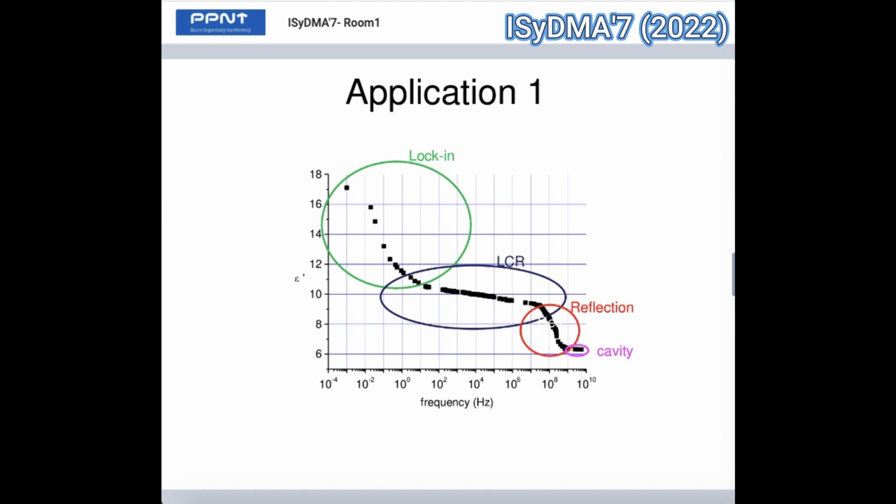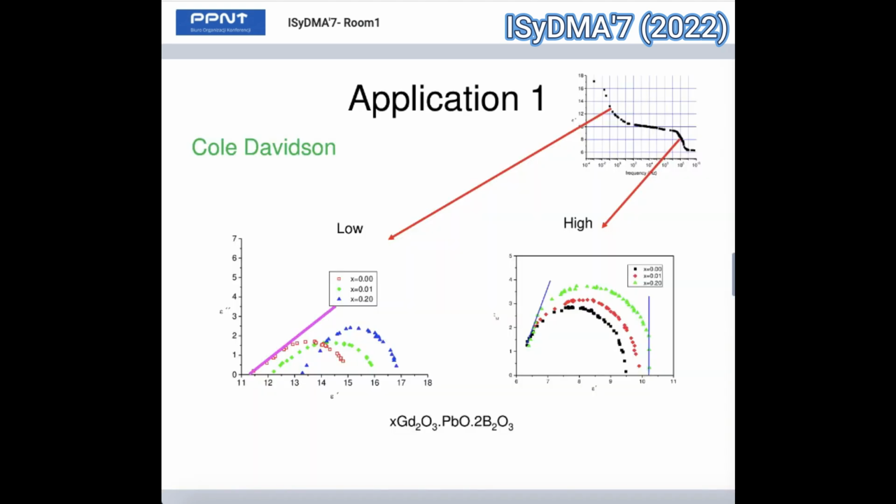And at very high frequency, let's say microwave frequencies, I use a cavity resonant method. That is a method that, in my case, for each cavity we can use only for one particular frequency. Usually, I use the TE10 mode. Okay, so then I represent here the Cole-Cole plot.